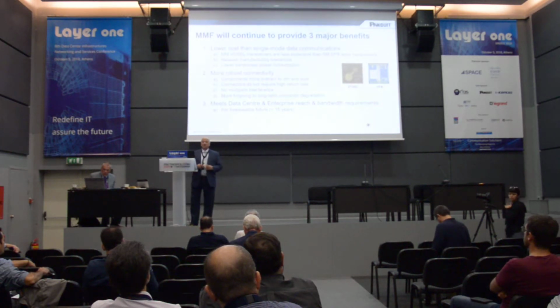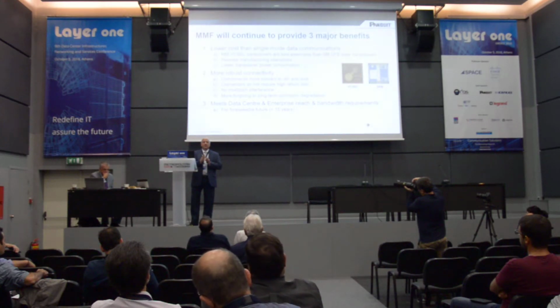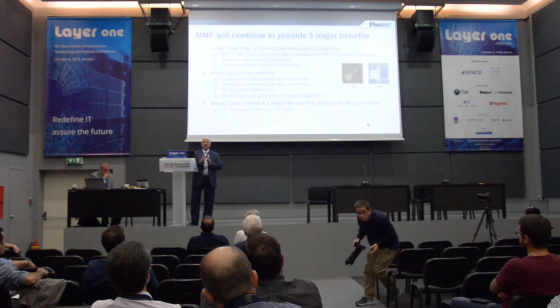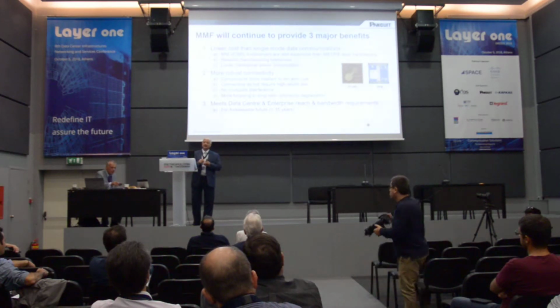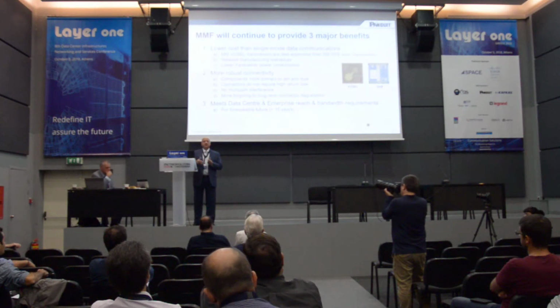The other reason multi-mode has benefits is in terms of size. Not only the size, but with single mode connectors, when you get scratches on them, those cause reflections. As you start cleaning connectors and you add scratches, you get reflections. That's measured in return loss. You want a high return loss, so you don't get many reflections.